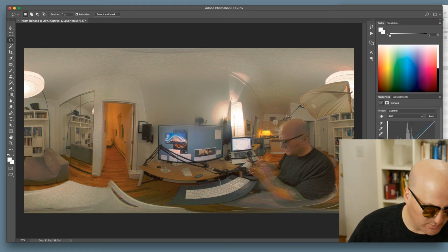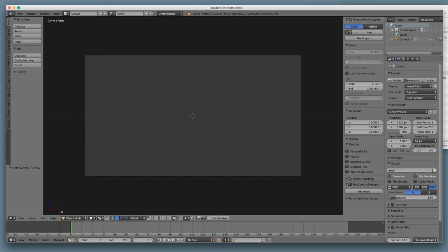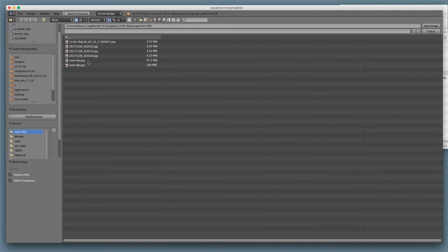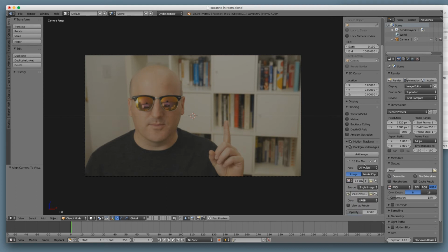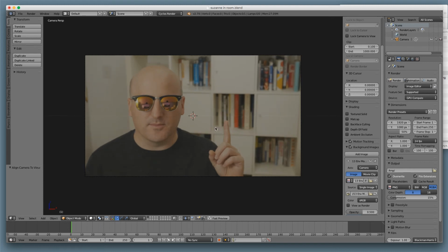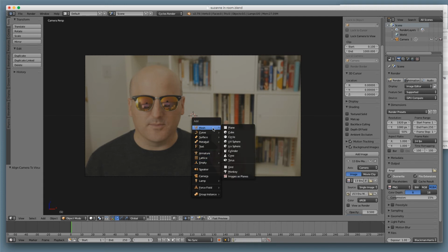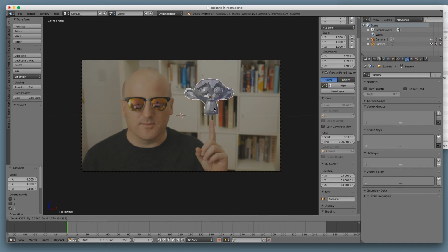All right, so I'm going to go ahead and open Blender. Okay, so I'm going to go to the very front. As a background image, I'm going to go ahead and import the very first clip of this video, or very near the first clip of the video. And that's going to go only on camera. Great. And then I want to add a Suzanne here. So we'll Shift A, add, mesh, monkey. Okay, let's bring her right above where I need her.